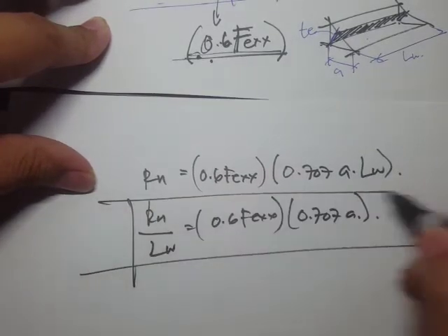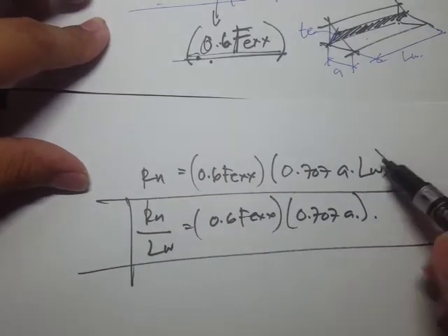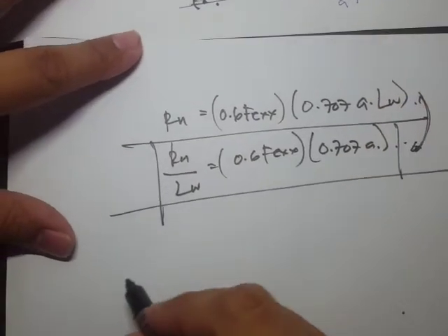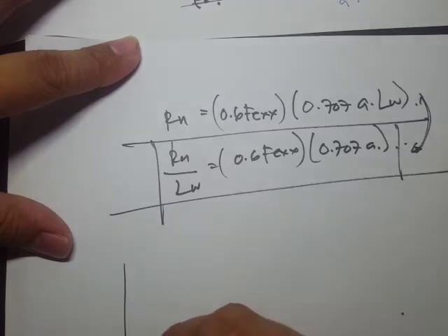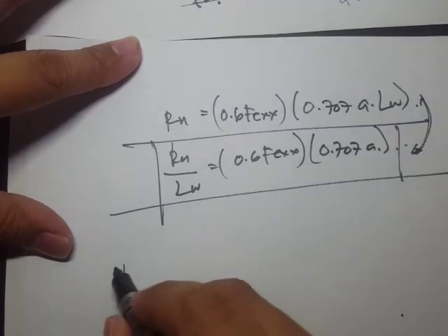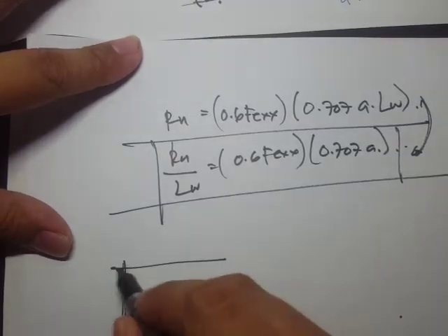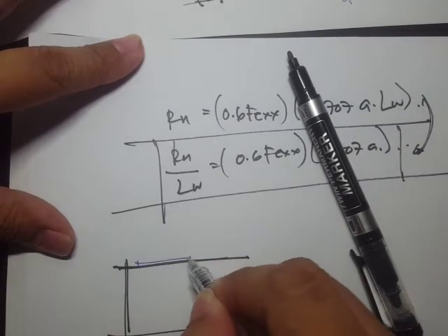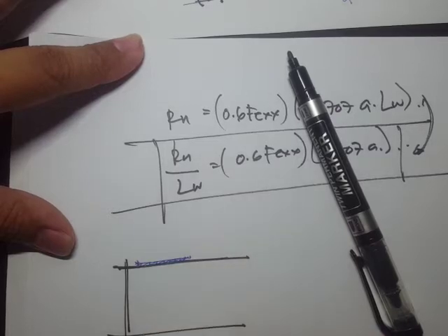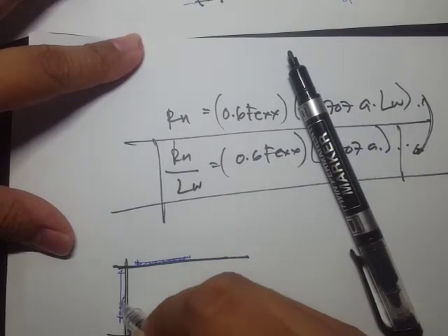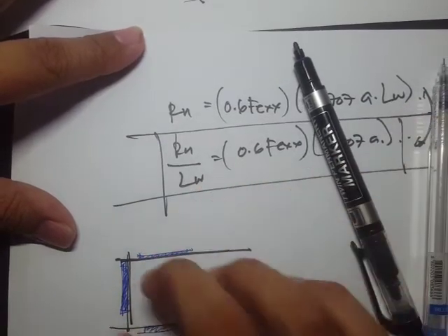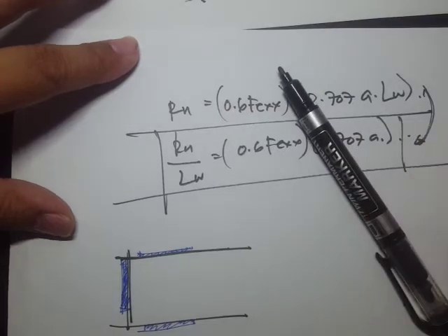Okay, so why do we have to transpose this equation to this one? It's simply because, recall, there's a different capacity if we're welding along the load direction, or if we have a weld in this perpendicular direction, we have a different capacity.